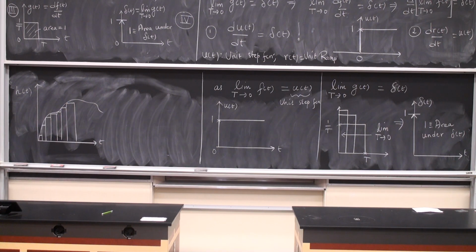so on and so forth. You see, I can approximate it as a series of rectangles, right? Because the area under the function is the same as the area of all of these rectangles put together. Now, each rectangle is a pulse. So if I know how the system responds to one of these, which is what we are going to achieve today, then the powerful thing is I can find out the response of the system to any arbitrary force applied by just summing up the responses of all of these pulses put together.